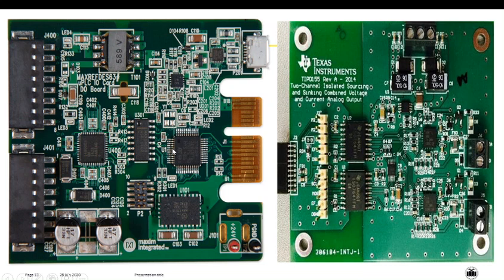Okay, so how do these cards look? This is a discrete digital output board, a discrete IO card. Maybe it is an 8 or 16 output discrete output module. This signal will be received, given by the processor, and that 12 volt or 24 volt signal will be converted to the appropriate signal using this circuit, and it will be obtained at these terminals.